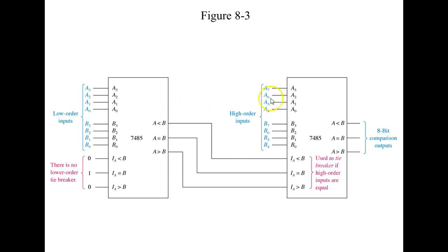And this is exactly what I used. I can't remember if I had to use 1 or I had to use 2. I think it was just one of the nibbles that was messed up. So I pulled out the bad transistors and put an integrated circuit on there. You didn't see it. The machine might still be working out there. I don't know.